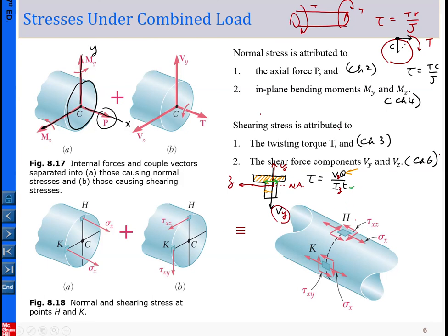Okay. And then for this case, I want to identify the directions of the shear stress. So the shear stress, again, should be in the same direction as the V here. Okay, so for this shear stress, you can see the cross section is our X plane. So that is in the X plane and pointing in the Y direction. Although it points downward, it is still in the Y direction. So this is the component tau xy here.